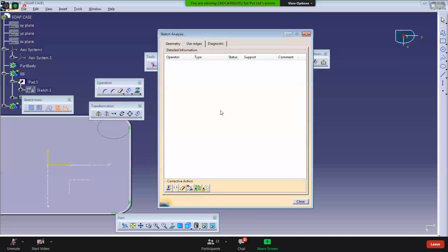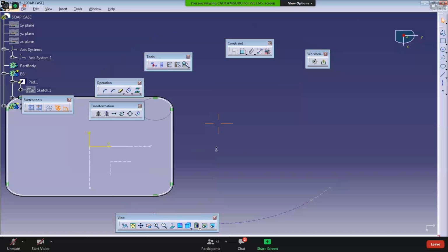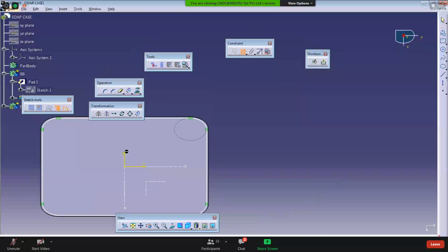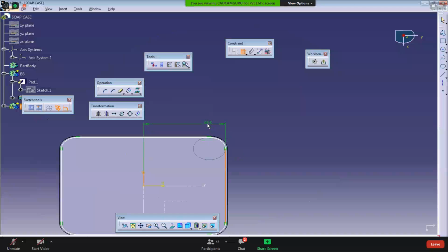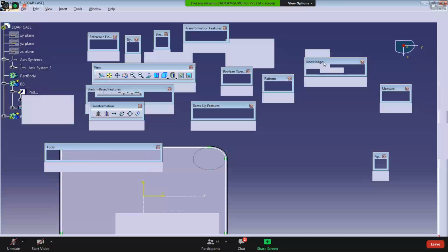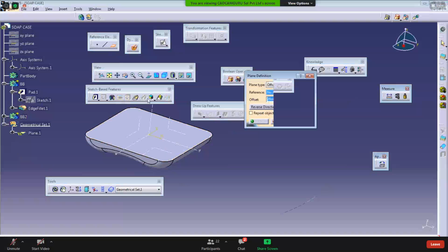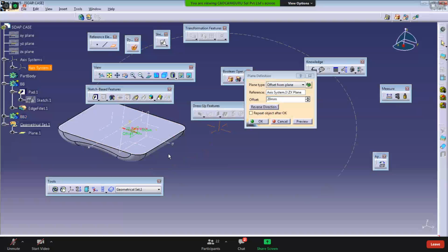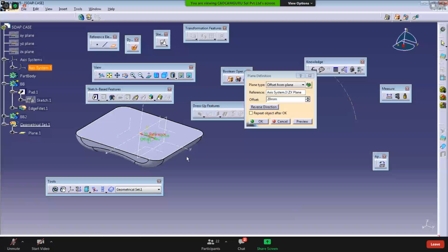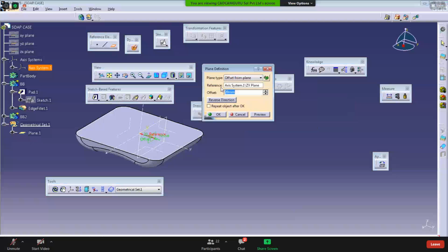It should be blank always in the Boolean operation. So I close it and define the sizes from here. So from this vertical dimensions to this. Okay, always provide the absolute reference dimension. Otherwise, what to do? I'm going to exit this. You introduce one more plane here. From this reference, how much total length is there? It is 140, right? So half of 140, I define this dimension 70.